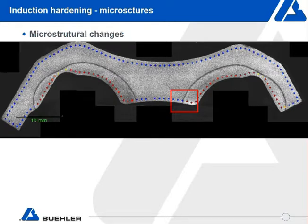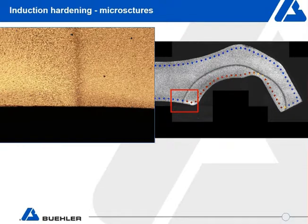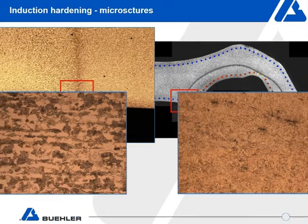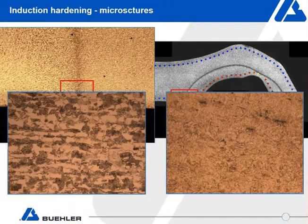And in this case, if I blow up that surface where I'm looking, you can see the transition from your core region, which is predominantly characteristic of ferritic and pearlitic microstructure, into the hardened component, which is predominantly or should be a martensitic microstructure. If we go to high magnification, that's the typical microstructure for this component that you would expect to see.